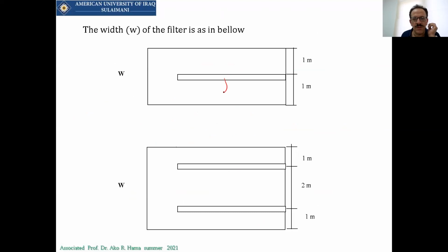If I have, this is 1 trough. This is the top view. If you want to check this one, there will be only one trough here, and this will be fixed from this wall and by this wall. So the water after the filtration, during backwashing, just goes inside this tank. And so the distance here is 1 meter from the wall to the center.